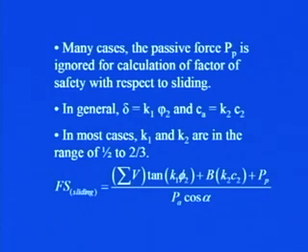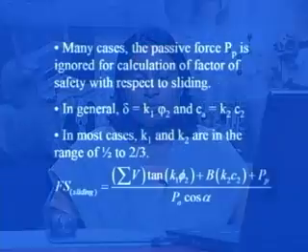You simply multiply this factor K1 to the value of phi 2 and you will be getting the value of delta, that is the angle of friction between the base slab and the soil. The adhesion between the base of the wall and the soil is equal to a factor K2 multiplied by the cohesion of the soil lying below the base slab, and that will result into Ca. In most of the cases, this K1 and K2 are in the range of half to 2 by 3. So, usually either it will be provided to you by the consultant or whoever is coming to you for the design of the retaining wall, or from your experience slowly you will get to know what these values should be, but usually they are taken between the range 1 by 2 to 2 by 3.